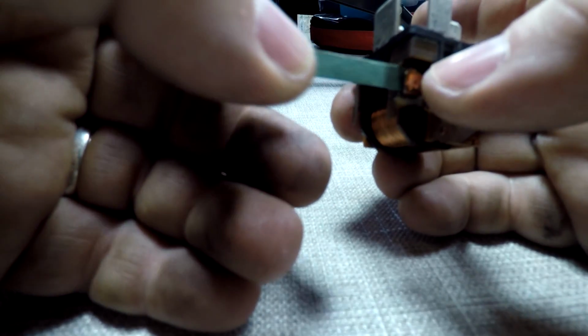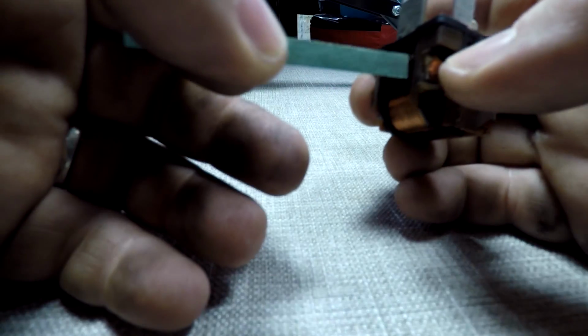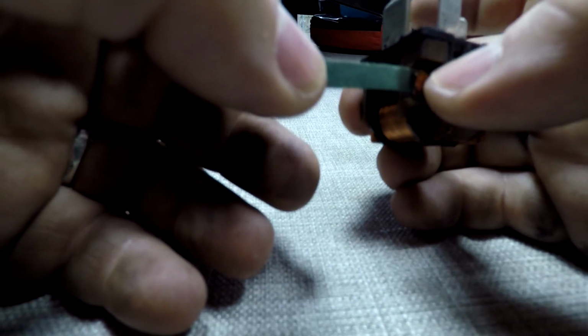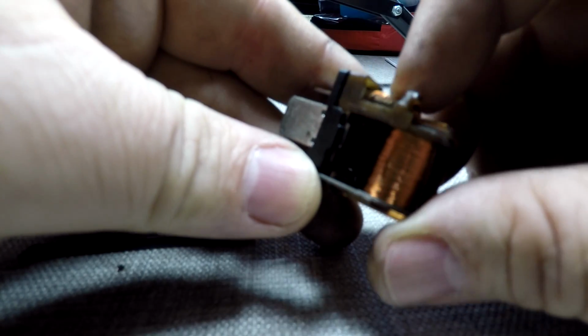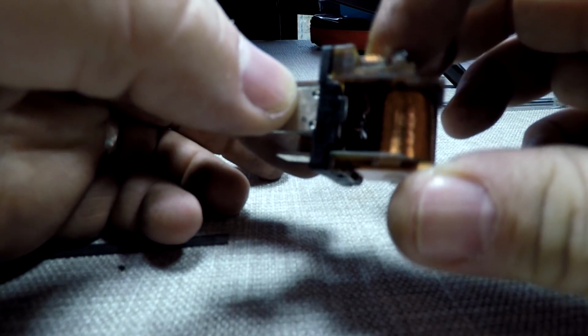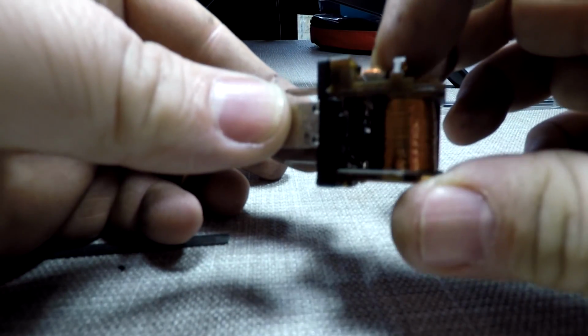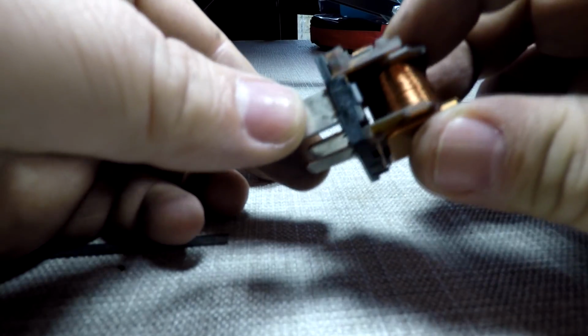Now, as I said to you, I haven't spent any money apart from a fuel filter on this. This is all part of my diagnostics. I could have just changed this over and then hoped for the best, but I'm only doing this to show you what's inside that relay. As you can see there, it is just one little contact that opens and shuts when the voltage is applied to that, and when it closes it allows the current to flow through the big terminals there. And if that is intermittent or dirty under load, then there's a good chance that that could be giving us our problem. So I'm going to put this back together now, and we're going to give it a test.